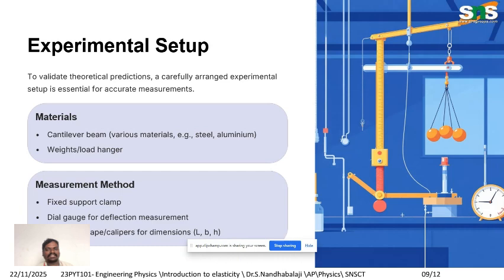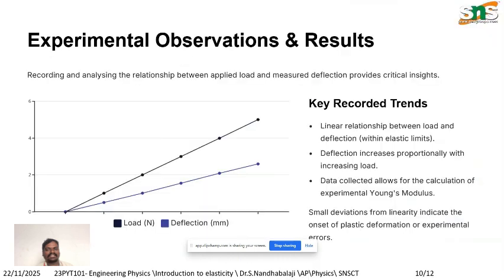Resultant discussions of this theory and experimental method, shown in the graphical method as a comparative analysis, reveal accuracy: theoretical and experimental values typically show close agreement for small deflection. The difference helps validate the foundational equations of beam theory. Factors affecting deviations: measurement error, dial gauge level, and beam dimensions, non-ideal fixed support condition, material non-uniformity, initial imperfection in the beam.